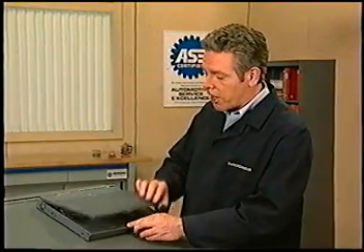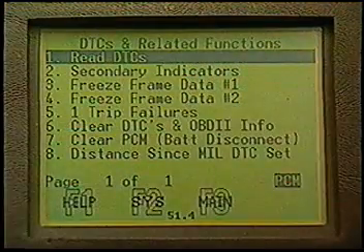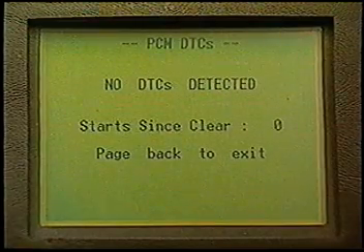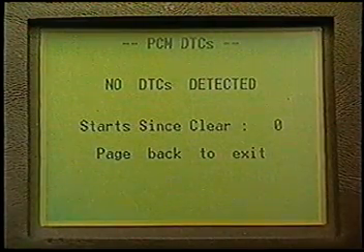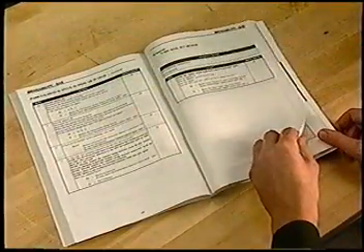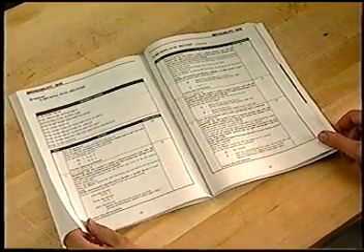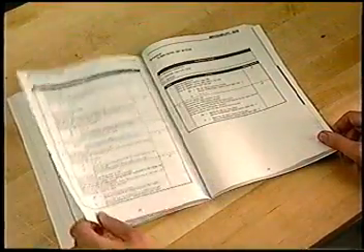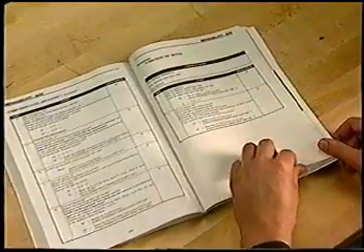While vehicles today require more sophisticated technology than ever, it's important you remember that generally much of what happens in their engines and related systems predates electronic control technology. If you come across a vehicle with drivability issues and no fault codes present, diagnosis may be no different than it has been in the past. For example, if you have a vehicle that is sluggish, the reason could be low fuel pressure caused by such things as a clogged fuel filter or a faulty pump or fuel pressure regulator.